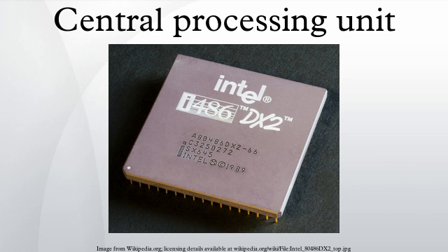In older designs, the portions of the CPU responsible for instruction decoding were unchangeable hardware devices. However, in more abstract and complicated CPUs and ISAs, a microprogram is often used to assist in translating instructions into various configuration signals for the CPU. This microprogram is sometimes rewritable so that it can be modified to change the way the CPU decodes instructions even after it has been manufactured.